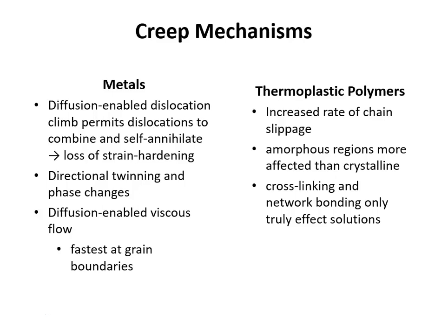So not only are you losing strength in terms of yield strength, you are literally deforming the material in service due to whatever load it's under in service. In addition to simply having diffusion-enabled dislocation annihilation and effective dislocation movement and deformation, you can drive all of the other mechanical deformation mechanisms like twinning. You can also enable complete phase changes.